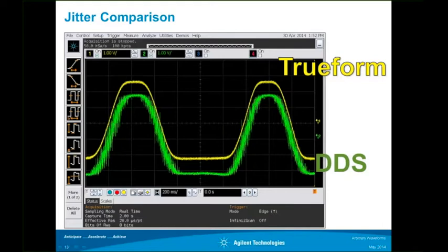With a roll mode on a scope, it's like a slow strip chart. It requires a repetitive signal to build the waveform, so it does it fairly slowly on the screen. Because of that, it actually digitally subsamples the signals in order to build what you're seeing on the screen. Since each waveform takes a little bit of time to build and sample, we can see the jitter manifest itself as voltage noise and jitter noise.